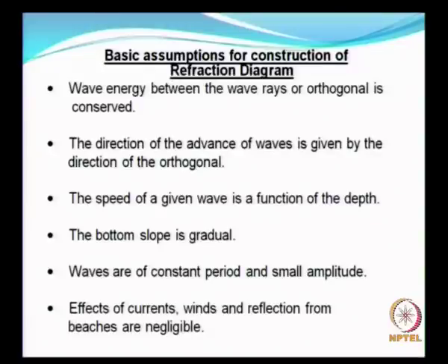While you construct the basic refraction diagram, there are some basic assumptions, some of which I have already told you. The first one is already mentioned. The second one is that the direction of advance of the wave is given by the direction of the orthogonal, because that is the wave ray. The speed of a given wave is a function of water depth. We assume that the bottom slope is gradual.